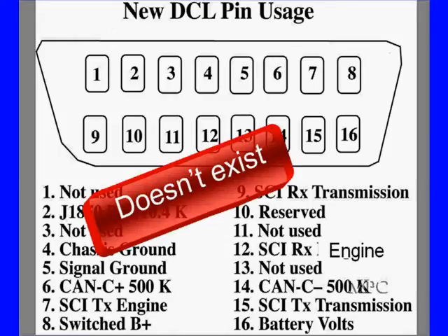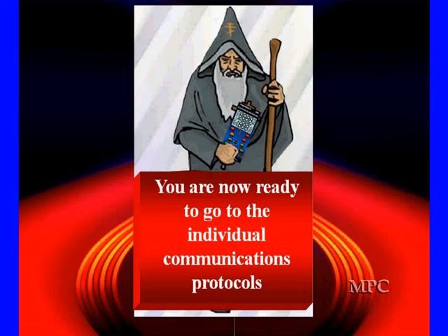You're never going to see pin uses follow everything it's supposed to. Look down there at the bottom of this. It says pin 15 is SCI transmission, transmit. The spec says it should be not used. It's for ISO 9141-2. So we keep saying it.